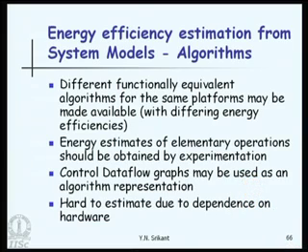So, we know what data flow graphs are. We draw them and then use that for estimation of energy consumption, assuming that we know the energy consumption of elementary operations. These are very hard to estimate due to the dependence on the hardware. So, depending on how accurate our energy estimation of elementary operations is and how accurate the data flow graph is, the estimate of the energy consumption of the algorithm for a particular platform will vary.